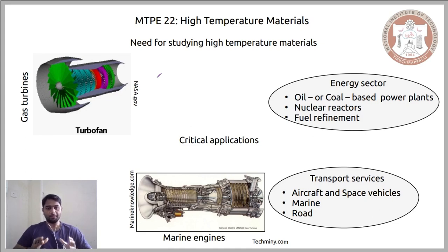So this is what happens in the gas turbines that we use in both aerospace applications and also in marine. We have a compressor that introduces air from the surroundings. We have a combustion setup that raises the temperature of the air and increases its kinetic energy, and this air is then sent to the turbine setup, which rotates and propels the vehicle forward.